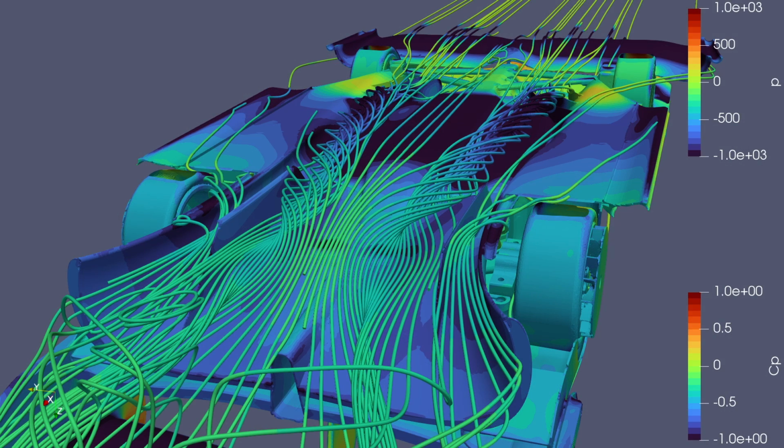So I'm not 100% sure what the ideal number of strakes for the underfloor are, but 4 strakes makes very little difference compared to 2 strakes and drastically increases the drag. So I went with 2 strakes.